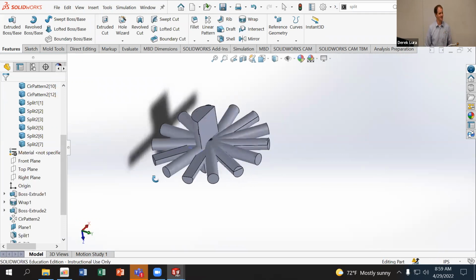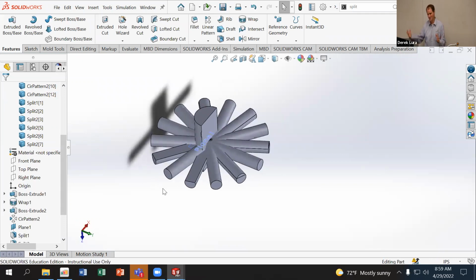All right, and you can go through and get really weird shapes and stuff like that using those different combinations. And again, once I have the geometry I want, I could fuse all that back down to one part. If you're doing this for 3D printing, make sure you do fuse back down to one part before you're done. But if you want to do multi-material printing, like you wanted the top half to be black and the bottom half to be yellow or something like that, then that is partly how you would do that. You would cut that part into multiple bodies, save those bodies as separate STL files, and then put them in the printer and align them together. And since they came from the same part, their origins are the same. So aligning them should be just setting them to the same starting point, right? So that's usually pretty easy.